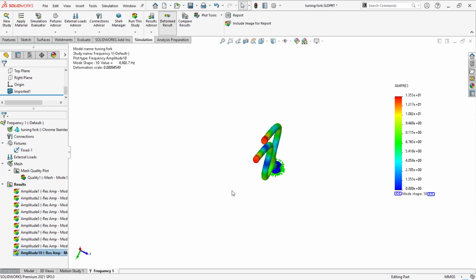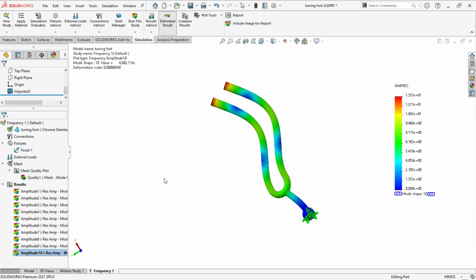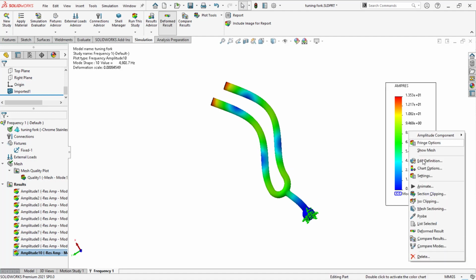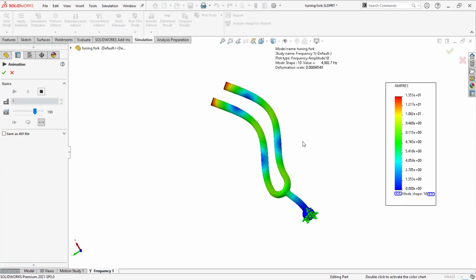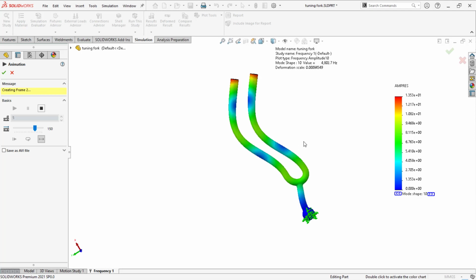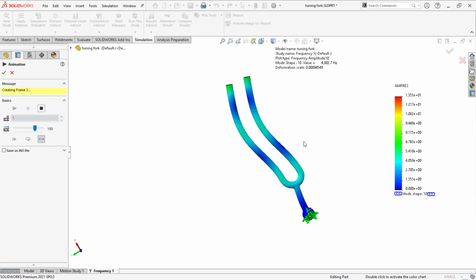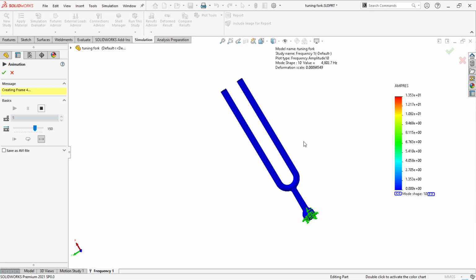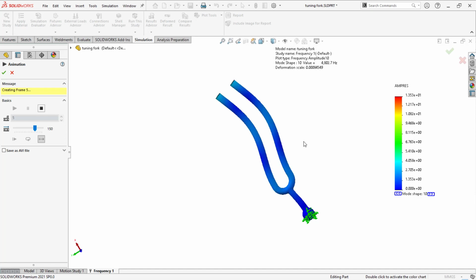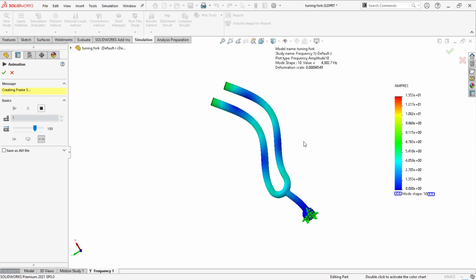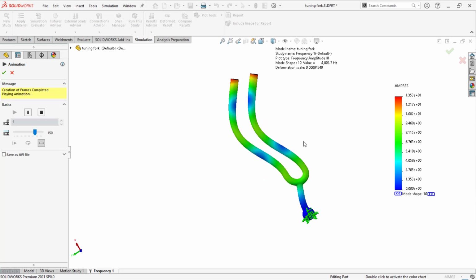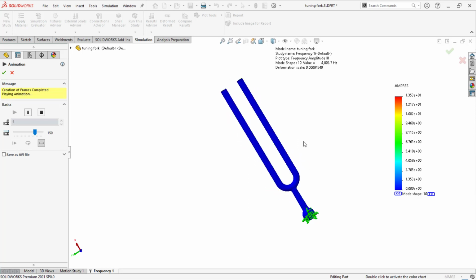So practically we'll consider the initial 4 or 5 natural frequencies because the least matters a lot. So naturally the natural frequency of any component will be in between the initial 4 or 5 natural frequencies. Okay, with respect to load applications as well, it is the same. And for the 10th mode, you could see this is how it's going to deform.